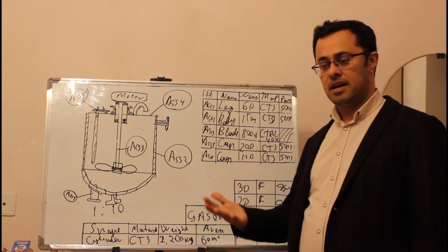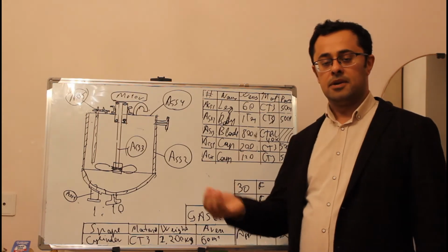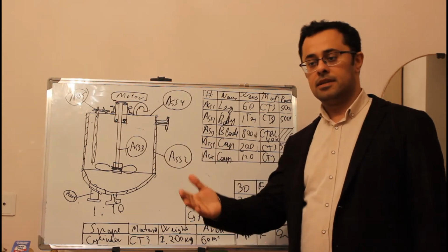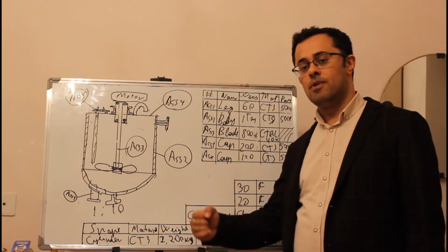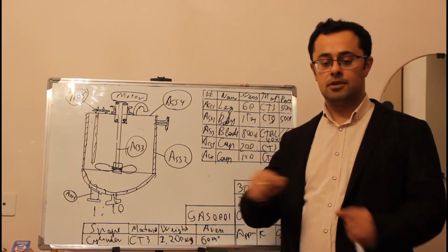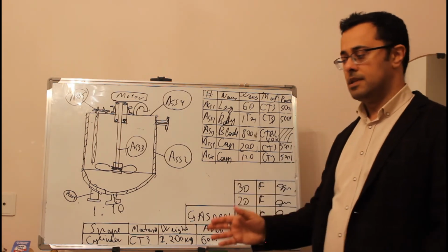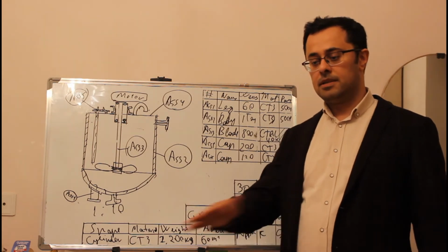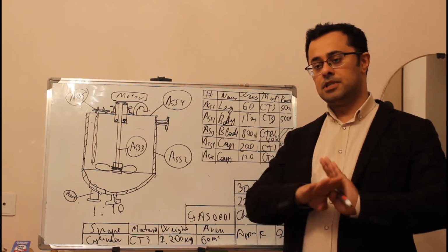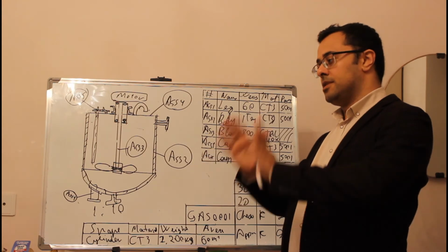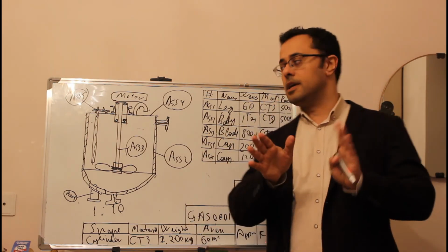Leg will be done in plasma cutting. After that it goes to welding, but before welding it goes to beveling, preparation for the welding. So there is a line for it: a plasma cutting machine, beveling machine, welding machine. So they put it there.